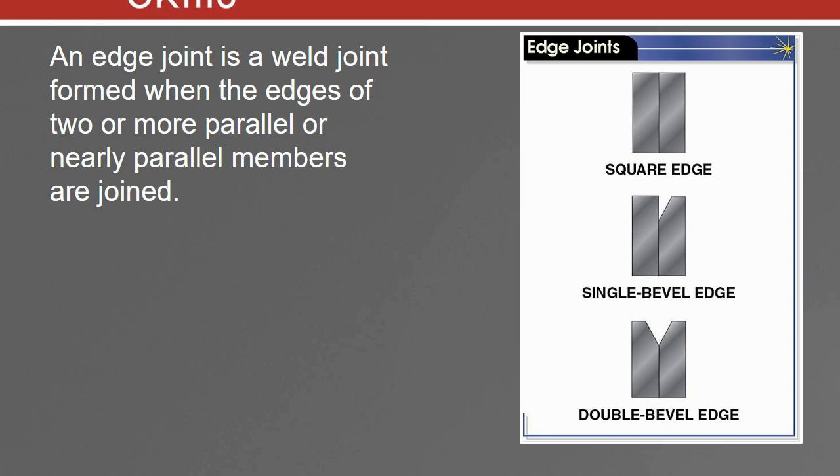Now, if this is a bigger piece of material, we might go in and take one of those materials and cut some holes in them and make either some slot welds or plug welds to support the center of those, and then grind them down smooth.